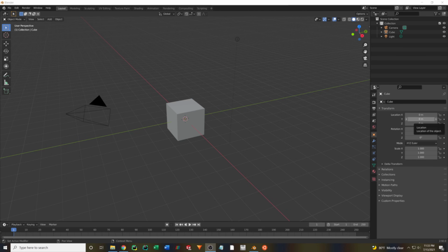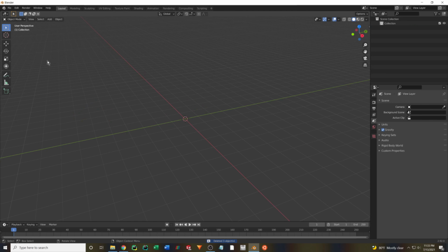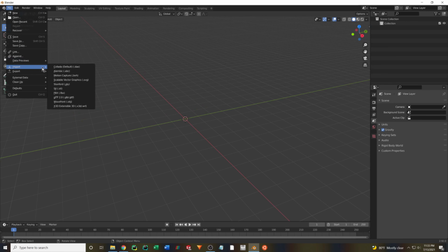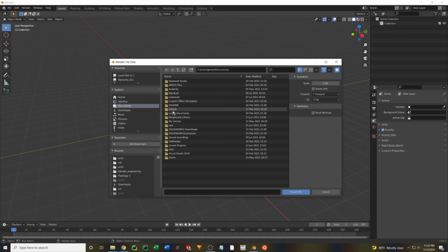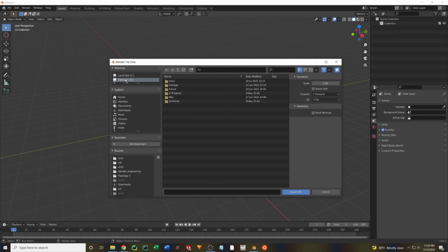First, open a general Blender file. Press the letter A to select all, then delete everything from the workspace. That way we can start with a nice, clean, empty workspace. Now we will import the STL files we created earlier. Because we saved them from the assembly, they will be in the correct relative positions when we import them.